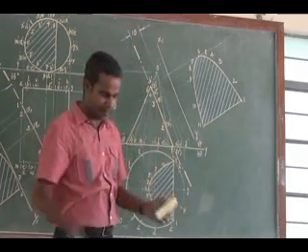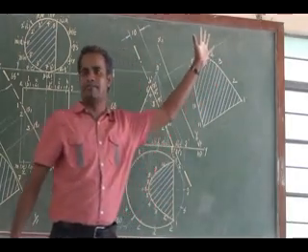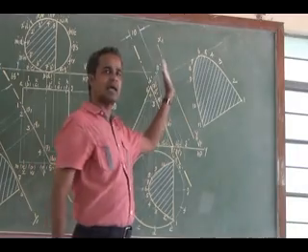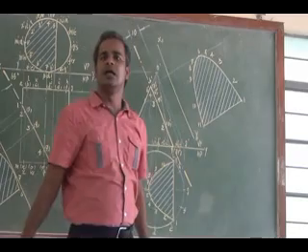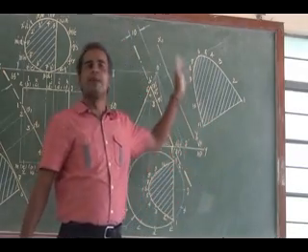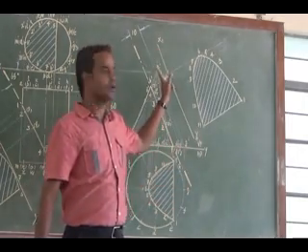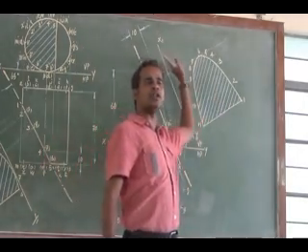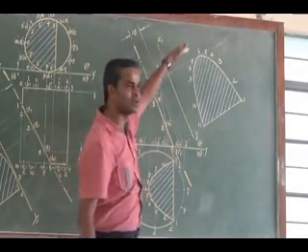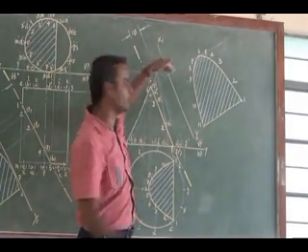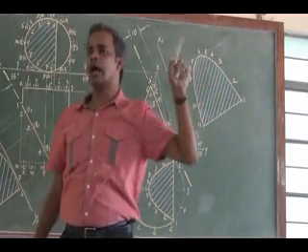So the cone is cut parallel to one of its generators. What curve will you obtain? Ellipse or parabola or hyperbola? Parabola. So the true shape of the cut surface will give you a parabola if the cone is cut parallel to one of its generators. If I look at the cut surface perpendicular to that, the true shape will be a perfect parabola.